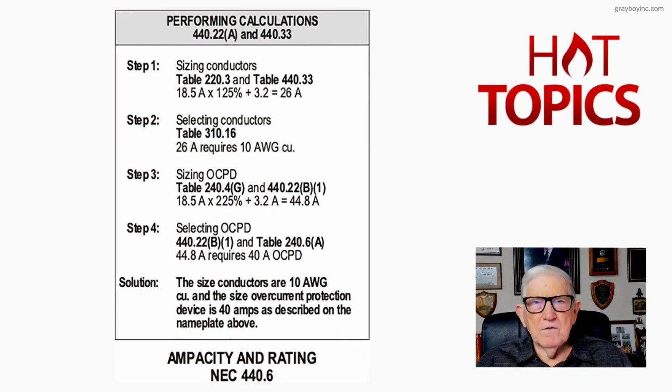Now let's look at this figure 19-1B, and we want to look at the code first so that we get a good feel for this individual branch circuit where you have to perform the calculation, because the nameplate branch circuit selection current does not list it for you. So first of all, let's go over to page 338 in the NEC, and on the right-hand side of the page, we pick up part 4, branch circuit conductors, and that's our part.